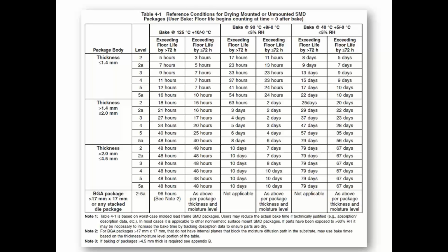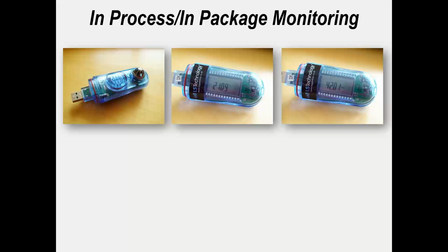And also when we talk about rework and repair. So baking boards prior to rework and repair is not uncommon within the industry, because you've got the components which may be sensitive, and you've got the adjacent components which may well be sensitive. So again, you've got to think about that. There's no point in repairing a board if you damage another half of it during the rework cycle. So understand the components. Some are very sensitive, some are less sensitive than others, but it's understanding that whole phenomena.